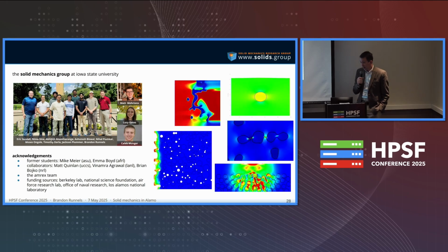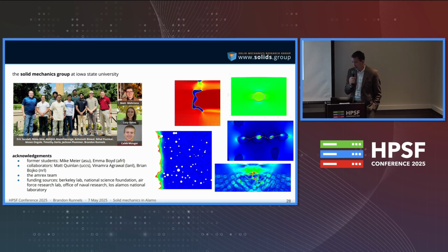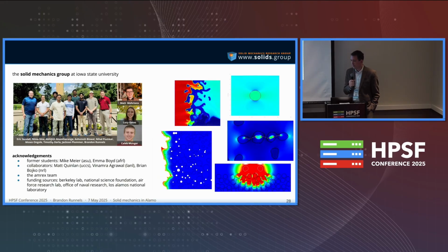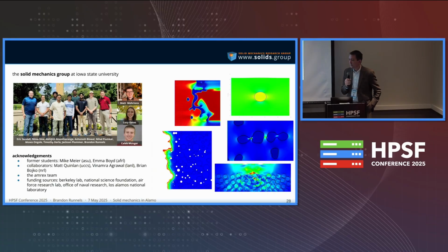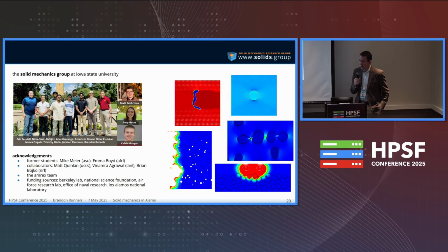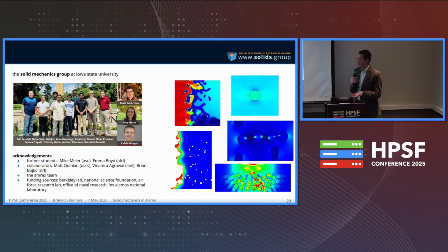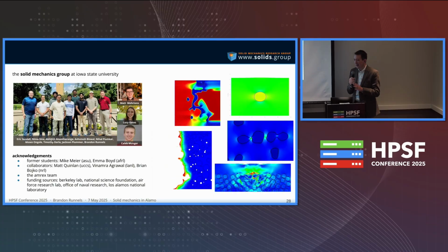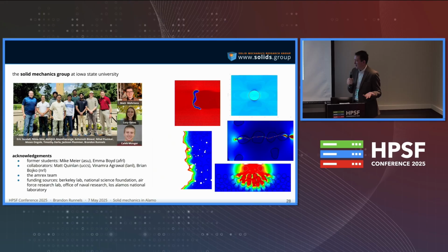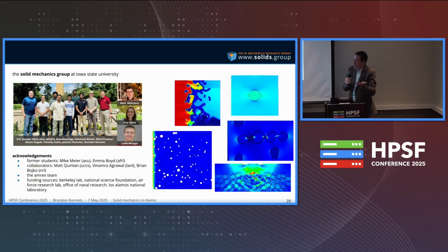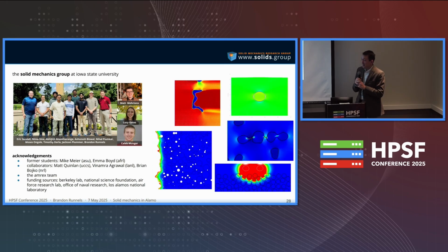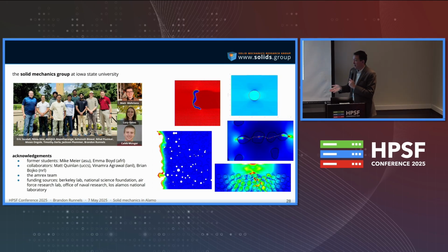You mean like EB, like embedded boundaries, or? Just everything that you're doing with like a diffuse representation of whether it's a cracked surface or an internal boundary in the mesh for the topology optimization example or whatever. So because so much of what we're doing is phase field, we're pretty deeply rooted in this idea of diffuse boundary mechanics. I will say the advantages of diffuse boundary methods are not strictly computational, but they're scientific as well. It's just very easy to formulate kind of arbitrary physics in that context. Certainly not close to the idea of moving to other types of boundary representation, but so far it seems to do the job.